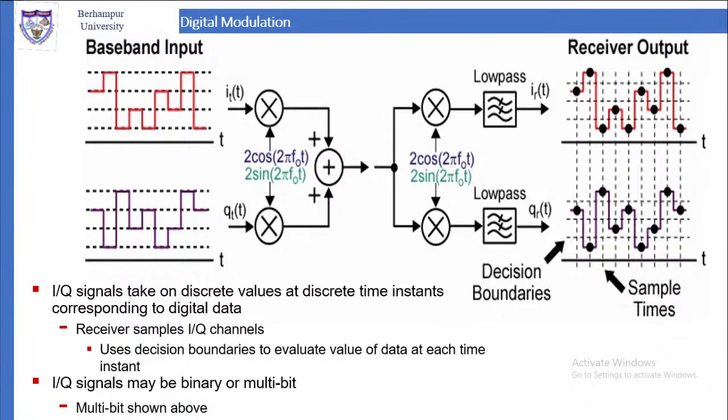Now if the output is 3.5 volt, what will you do? Is it 0 or 1? We have decided that 0 is 0 volt and 1 is 5 volt. We have now 3.5 volt. Will it be 0 or 1? Usually we take this to be 1. Suppose the output is 1.5 volt, we take it to be 0. What we do is, between 0 and 5 volt, we fix a threshold. Below that threshold everything is 0, above that threshold everything is 1.